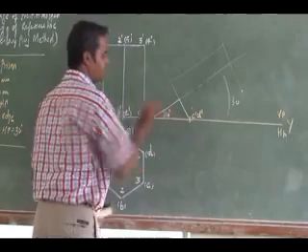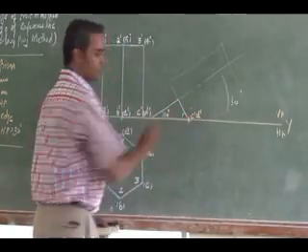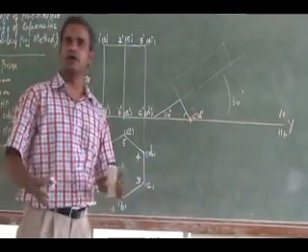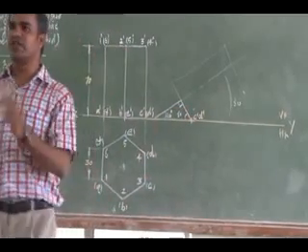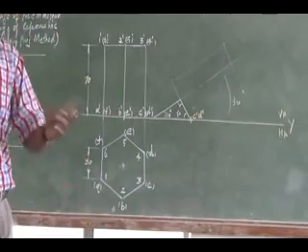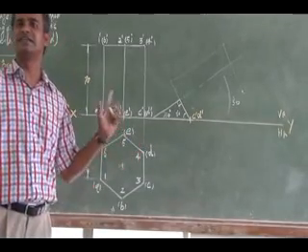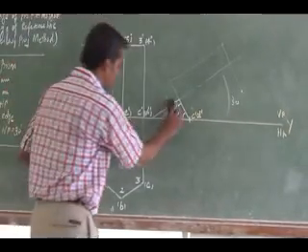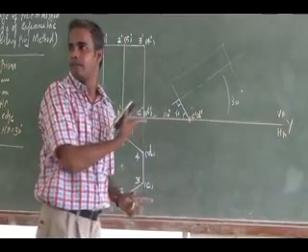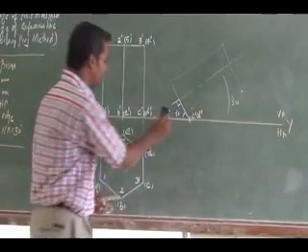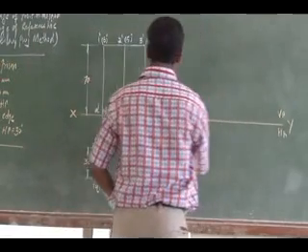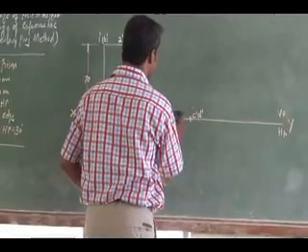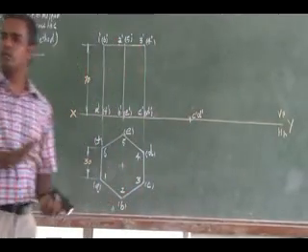If this is 30 degree, what about the base inclination here? 60. Okay. So 90 minus 30. This is perpendicular. This will be 60 degree. So if the axis is 30 degree inclined, you use the base inclination as 60 degree. Is it clear? So axis is 30 degree. You convert it to base inclination. So what I'm going to do? I'm using the base inclination as 60 degree.